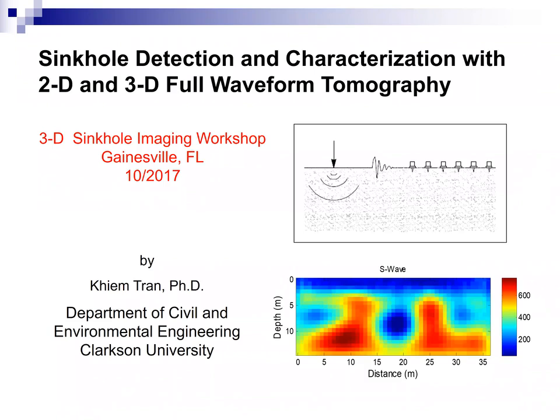We generate a seismic wave, propagate through the medium, carry the information of the soil and rock, and then measure on the surface. And then we do the waveform analysis to extract the material property of the subsurface structure. Here we have a shear wave velocity profile. We have a blue zone on the top here, soil. The red area here is limestone. The blue zone inside the limestone here is a void. So the goal is to measure the data on the surface and then identify the embedded void, go to 50, 60 feet depth like we usually do with our equipment.